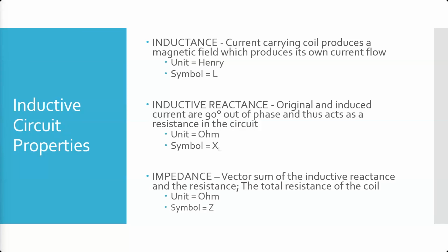With eddy current testing, we're looking at a change in impedance in the coil, okay? And it can be the same when we get to probes. It can be one coil that is providing the magnetizing current, and the tester is looking at a change in that coil. We sometimes have multiple coils where one is called a driver. That's the one that induces the eddy currents. And then we have a separate coil that's called a pickup that is going to be affected by them. But at the end of the day, the tester is handling what type of probe it is.